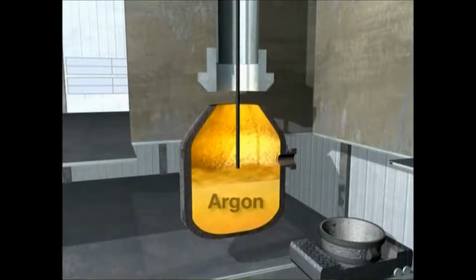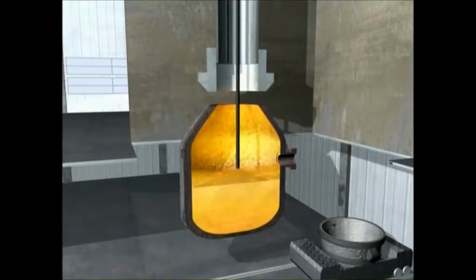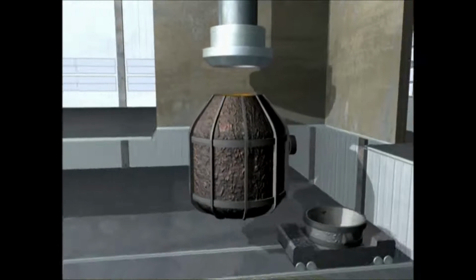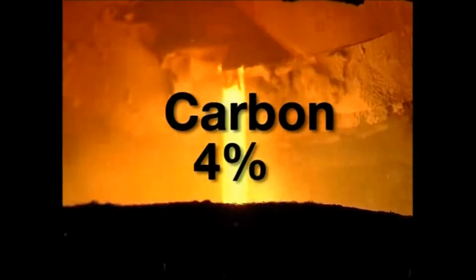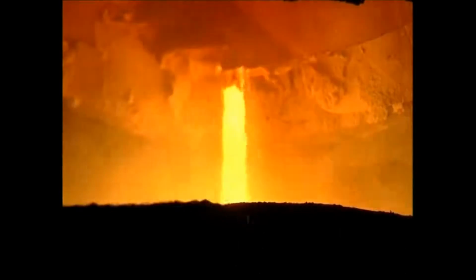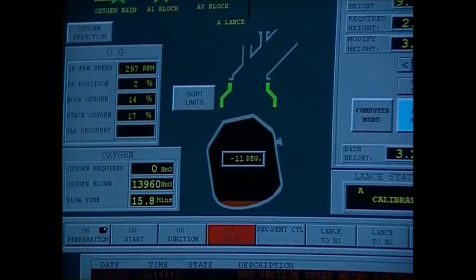Refining can be assisted by injecting argon, nitrogen or oxygen gases through the base of the vessel. And a sublance is used to measure carbon and temperature during the blow to allow final adjustments to be made. During tapping, alloy additions are also made to adjust steel composition. By this stage, the carbon has been reduced from around 4% to about 0.05%. Finally, the vessel is tipped to remove the slag for recycling.